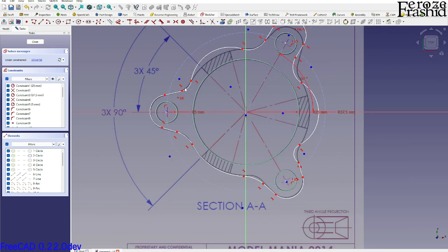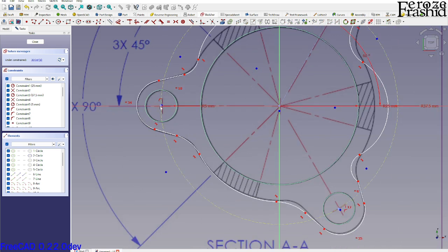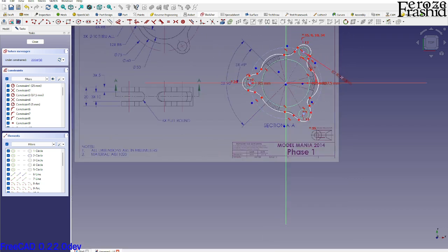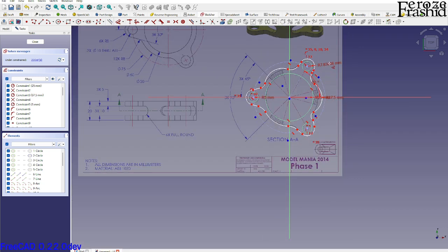Okay, so first of all, I want to go ahead and make all of these three equal. So select all of those, hit E on the keyboard, and then take this and make it coincident. So that's C. Now that is fixed. I probably want to do that on here too, and here. Okay, the next, let's fix the dimension to it. So that dimension is going to be 8.